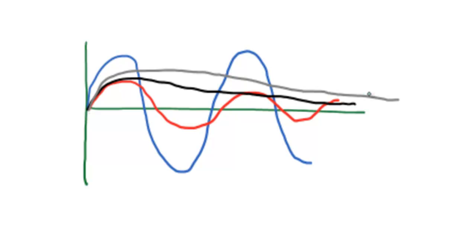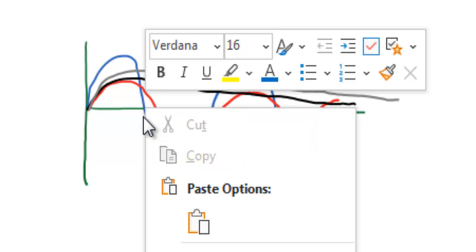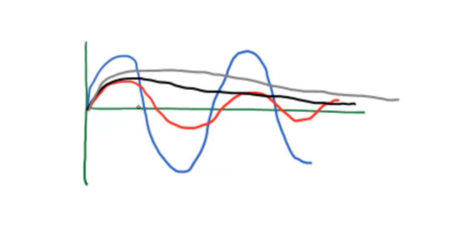But in this case, you can see that once the thyristor is turned on, the current starts flowing through it. You can look at the waveforms and see that this current comes to 0 quickly first with the undamped system. Next it comes to 0 with the underdamped system. But in case of critically damped and overdamped systems, this current never comes to 0.